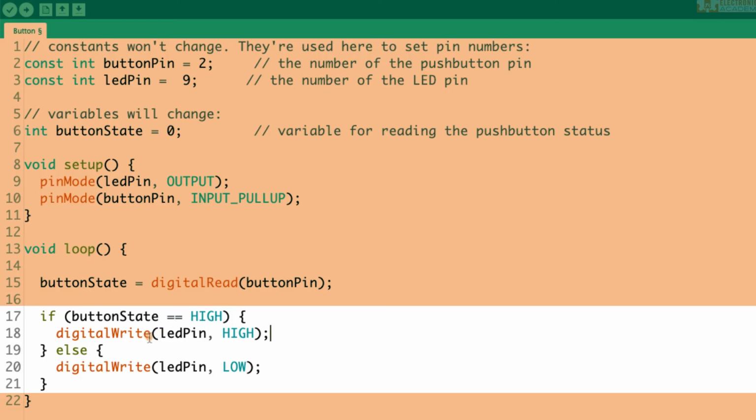And in this case, we come to another super important Arduino function, digital write. So we had digital read a second ago. That's for reading digital inputs, either on or off inputs. And digital write is for creating an output on those digital pins, either a high voltage or a low voltage. So digital write is going to take two values. First, it needs to know what pin to apply the voltage at, and then either a high voltage or a low voltage. So in this case, the voltage is going to be high. We want that LED to be on if we are not pressing the button.